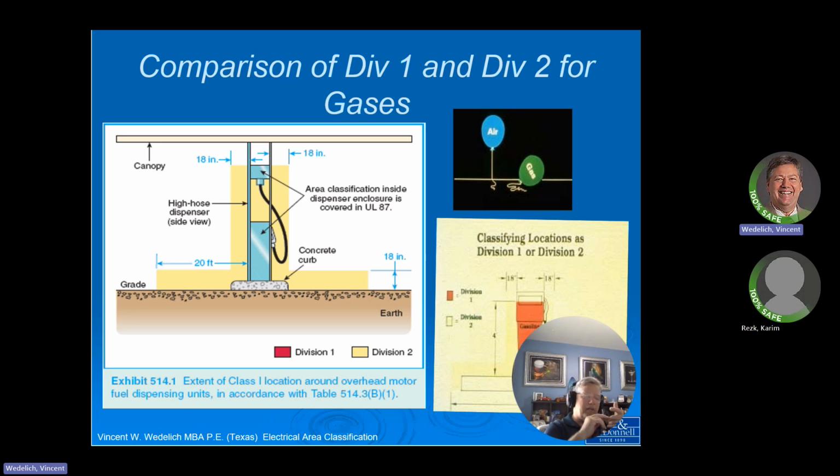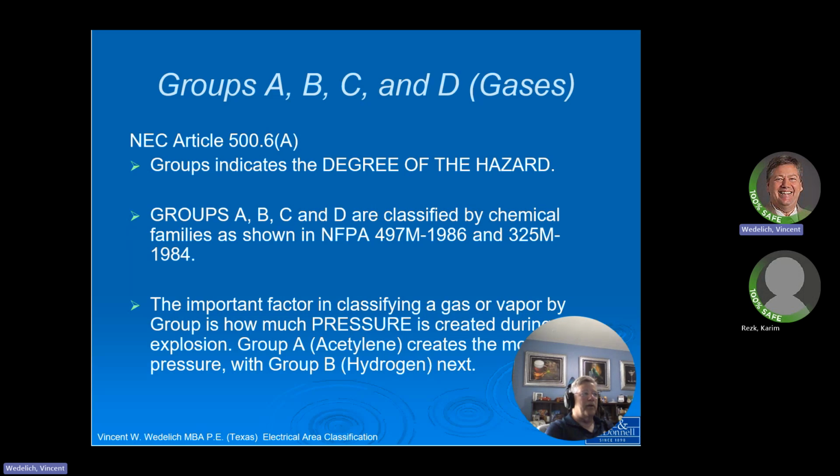We're going to say, okay, well, it's Division 1, it's always there, guaranteed, 1 to 10 hours or 10 to 1,000 hours of the year or more, it's Division 1. If it probably could be there, a leak source, certainly, then you're a Division 2. So now the only thing we're missing is what is it, right? If it's Class 1, Division 1 or Division 2, what is the group? And that's what we're going to talk about now, is groups.